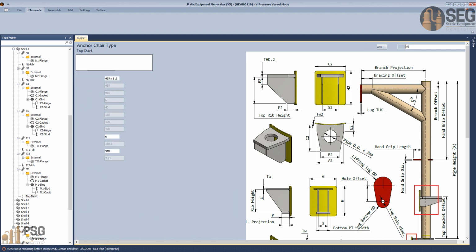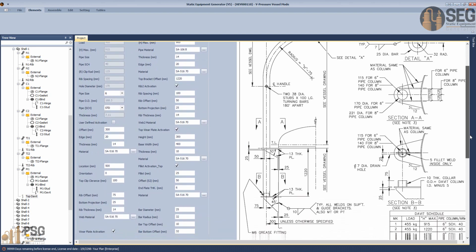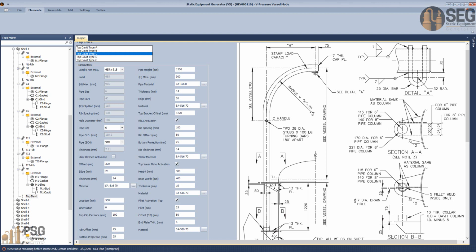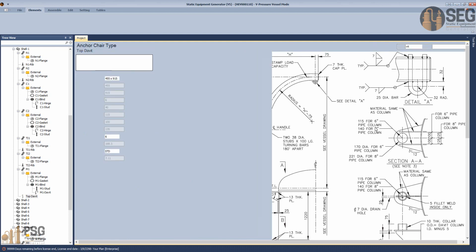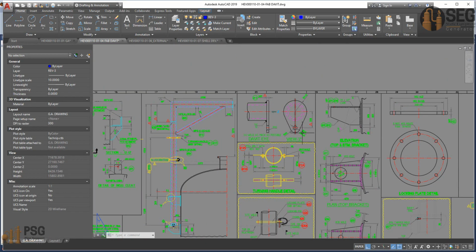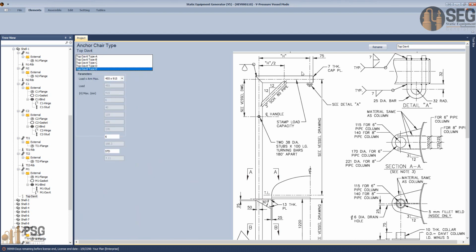Another type, which is type C, is related to another standard spec, so you can use this type if it suits your requirements. Another type of the top davit has a lifting lug that is just a U-bolt, but in our case it's a blade, so that type will not suit our requirement.